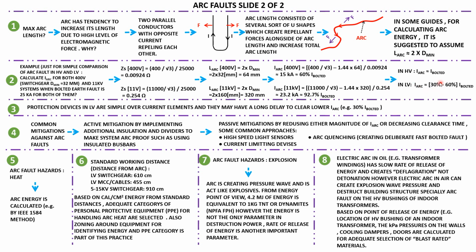And imagine if you have 30% of the bolted short circuit current and it is an arc in place. Normally it's very hard for these devices to clear the fault in a proper way, with a proper delay. And some of them cannot even detect any fault, whereas a massive arc is in place. So I'm not going into detail on that, as common mitigation against arc fault is a very broad topic, just a very small touch here.